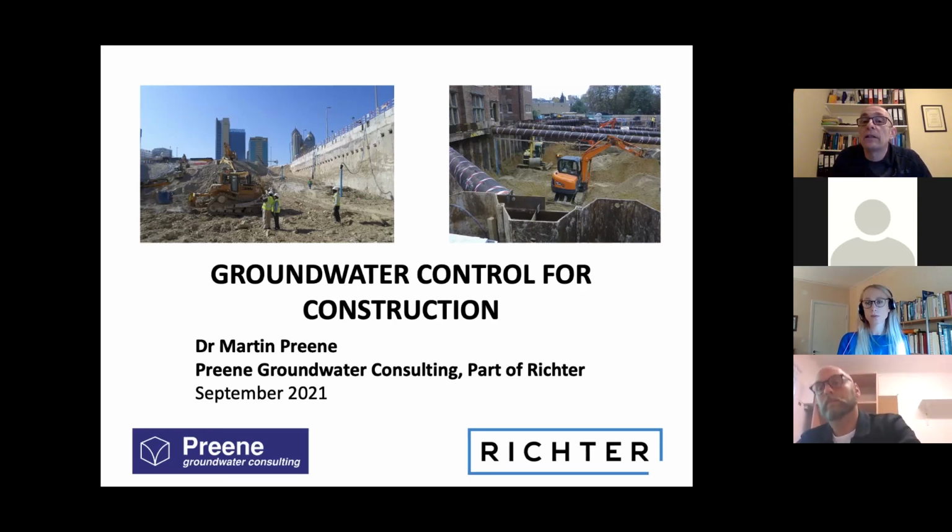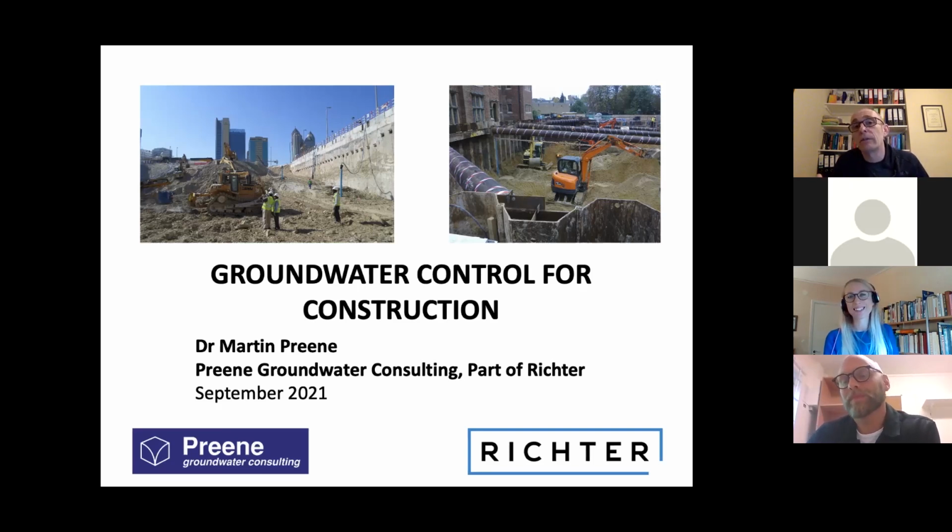And the other thing is, an exclusion method might have many benefits with risk, because let's say you are in the middle of a city in Sweden where there are many buildings on timber piles. An exclusion method could potentially reduce the risk of you damaging the neighbour timber piles, whereas a dewatering method might be much cheaper but would have risks with it. So again, not a great answer, I'm afraid, but that is one of the challenges of this field, is that there are so many different factors that a generic guide is quite difficult. Yeah, true.